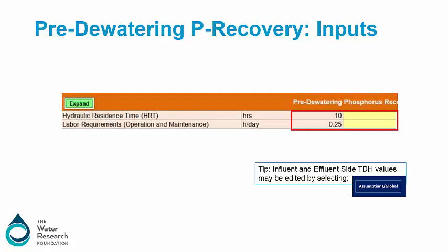Flow rate and HRT-based cost curves for post-dewatering struvite recovery were provided by Gerhard Forstner and his team at CMP. Pumping costs have been estimated using the influent and effluent TDH in global parameters. Aeration and magnesium chloride demand are estimated using typical airflow-liquid flow ratios and magnesium chloride per pound of phosphate ratios provided by CMP. Since these processes are proprietary, the user will not be able to customize these values.